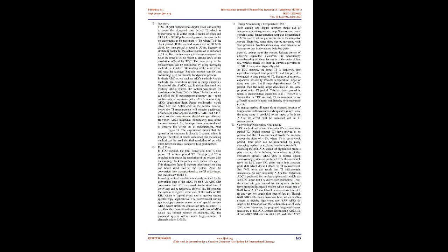In single ADC or two tracking ADCs method, analog method, resolution of the system is governed by ramp duration and ADC's number of bits. So, with ramp of short duration like 600 ns, and 16-bit ADC, resolution equals 600 ns/2 to the power of 16, equals 10 ps approximately. Very fine resolution of ps can be obtained using analog method. However, in conventional analog method, range is limited to few ns for obtaining ps resolution. This limitation is overcome in the designed integrated system by adapting to free-running ramp technique.